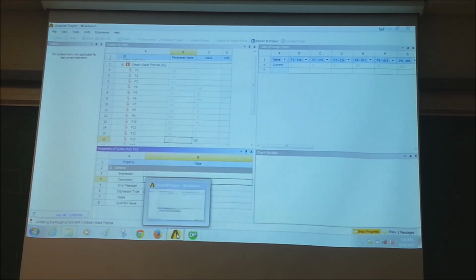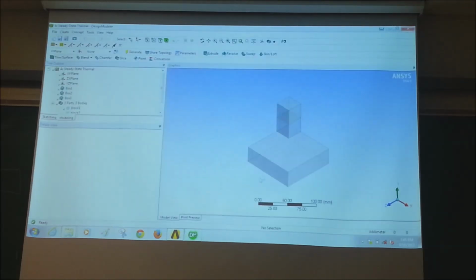So if I go to the geometry now, look what happened. It's up there, right? And now I can change the dx. What I will do is make it one-dimensional. We know it's L1 over K plus L2 is something, right? If it's all the same dimension. So let's make it all the same dimension for right now, so it can be nice and one-dimensional.